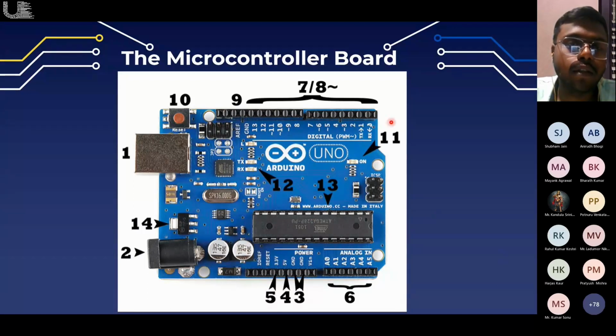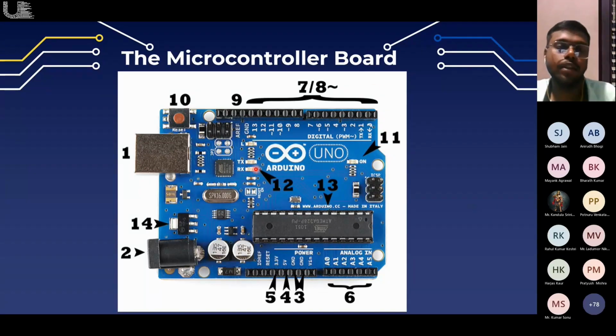Digital pins 0 and 1 are labeled TX and RX, and the arrow also shows the flow of data. TX means the data is sent out from the Arduino board, RX means data is received by the Arduino board. Whenever these pins are working, these LEDs will light up, so you can check whether the transmission and receiving process that you have coded is happening or not.